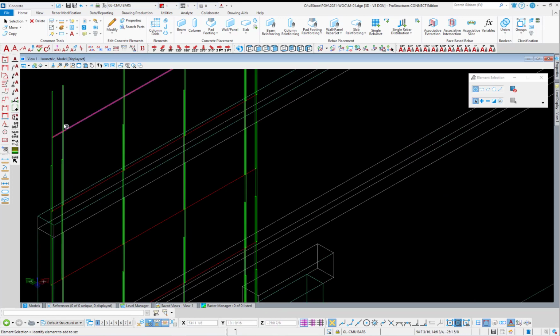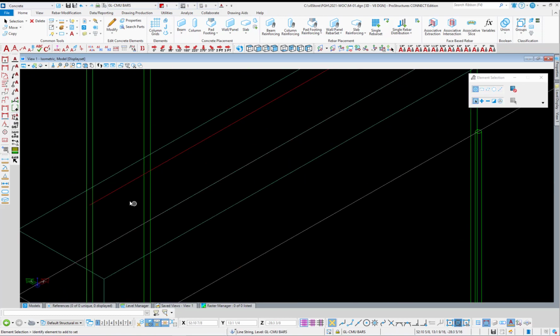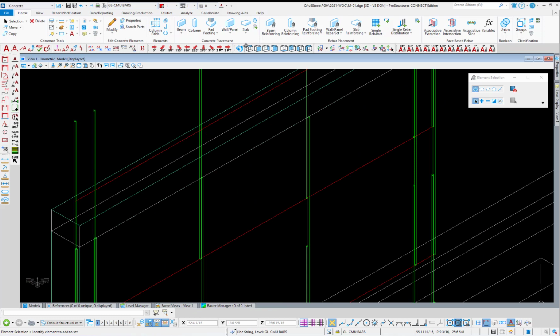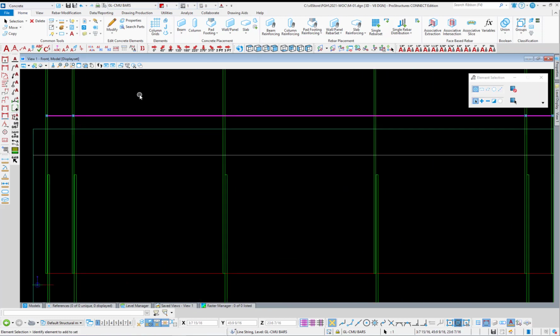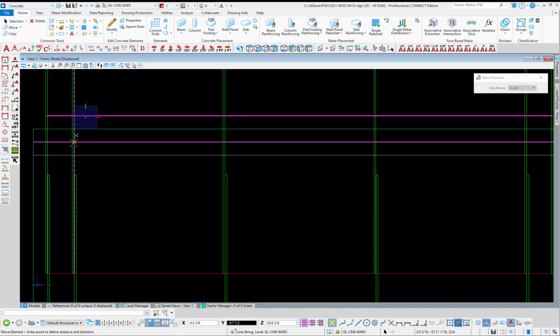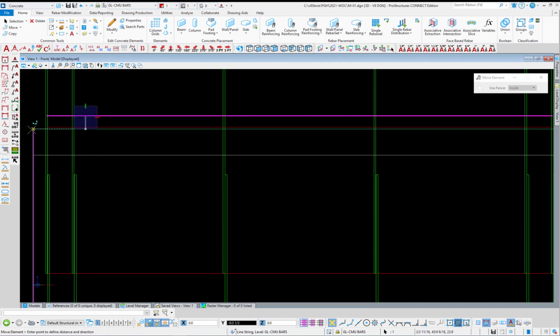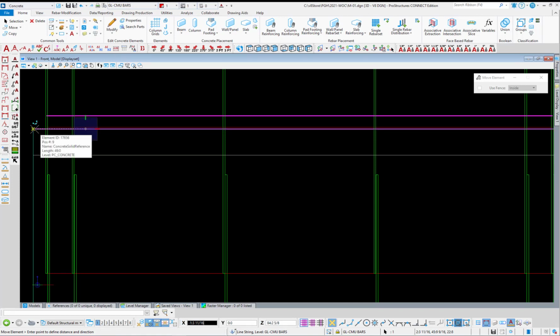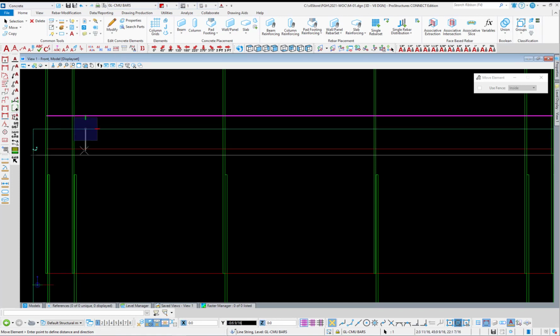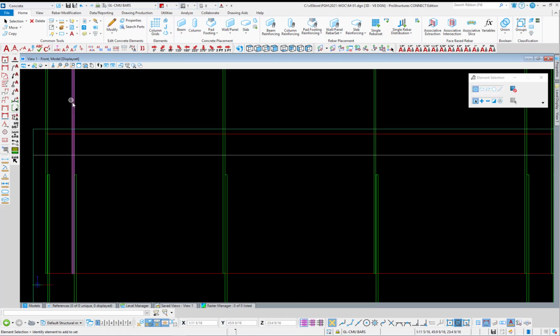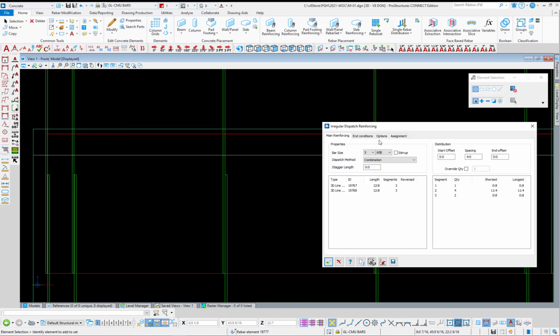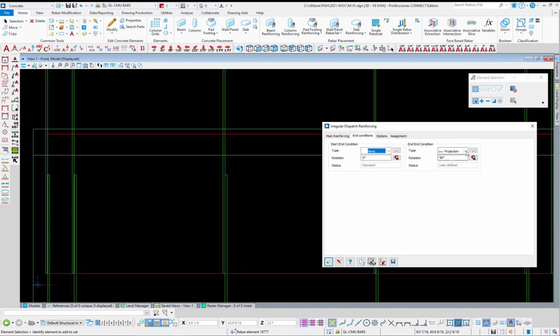And now you can see that we're actually outside the concrete. It's not a problem. I'm going to get rid of this bar. I'm going to get rid of this guideline. I'm going to get rid of that guideline. Now I'm going to rotate the front so we can see what's going on. And all I'm going to do now is double click. I'm going to move this guideline down that I've got selected, lock it in place, come to the top of concrete, O for origin. I'm going to come down 2 inches. Double click my reinforcing, and instead of having a projection for that lap length, I'm going to rotate that to a 90-degree bend. And I'm just going to save it.